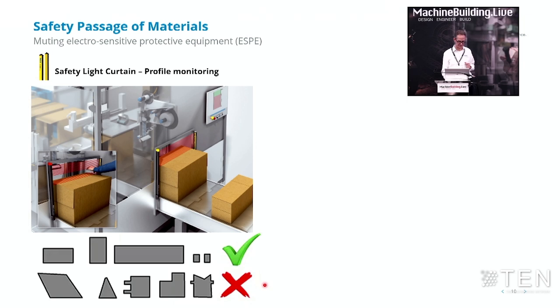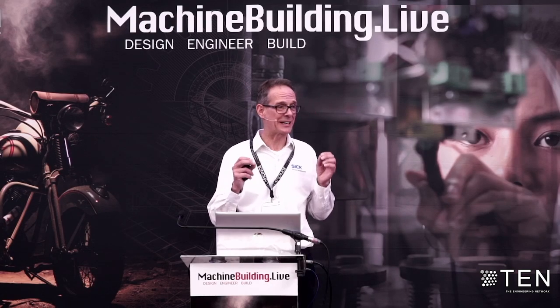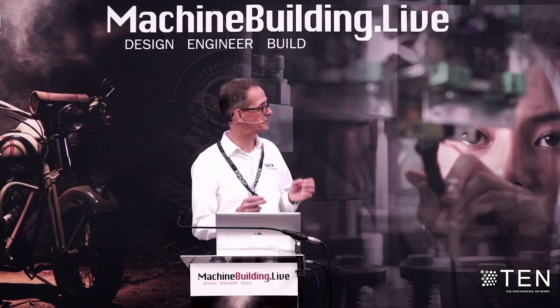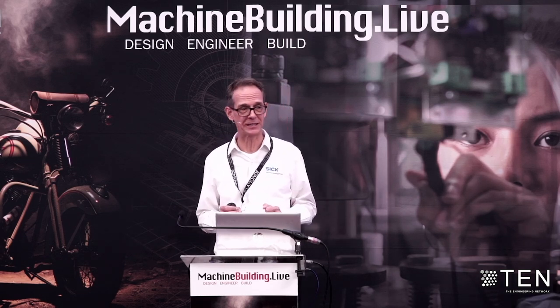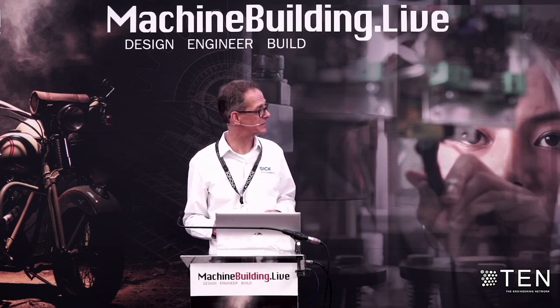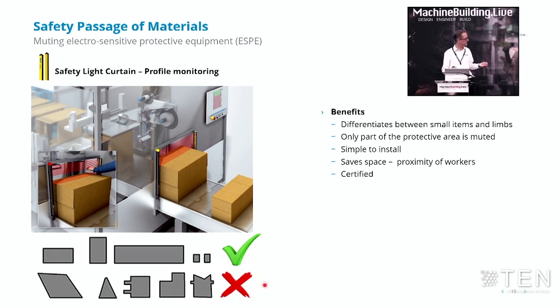So the benefit is, with classic muting, which I showed you at the beginning of the presentation with muting sensors, it's very hard to achieve this kind of application and differentiate between people's arms and limbs reaching into a machine. Only part of the light curtain is muted at any time. It's very simple to install, and it saves space. Again, it's a certified solution out of the box.